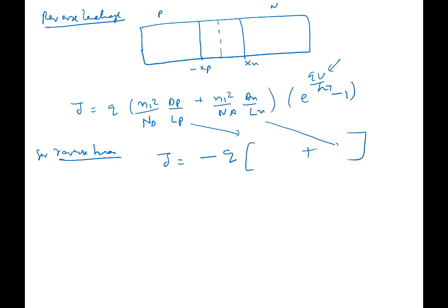Right? It's implying that. And just as we did the forward bias equation, if you don't want to use this equation, you can go back to first principle and derive this exactly by saying J equal to Jp at xn plus Jn at xp, then making the argument that Jp at xn is diffusive, and all those similar kinds of things, and you will end up getting the same equation that you will get here. But remember, one major assumption in this is that it's neglecting generation recombination in the depletion region.